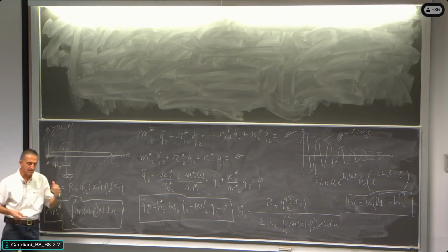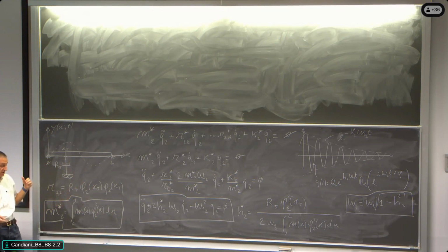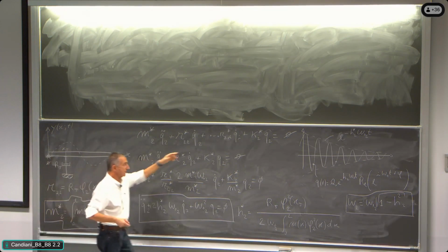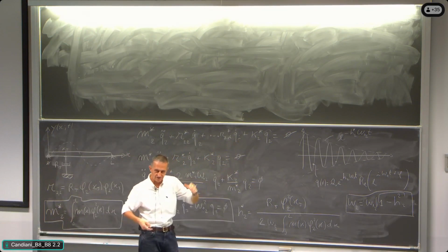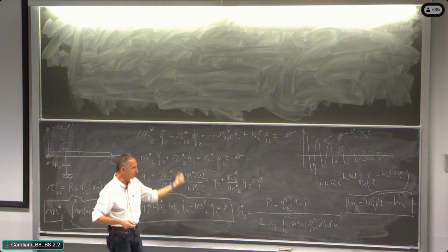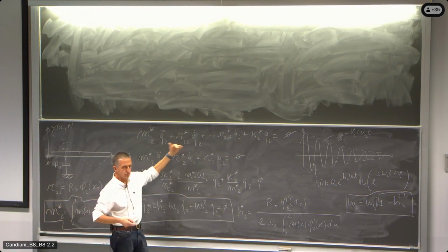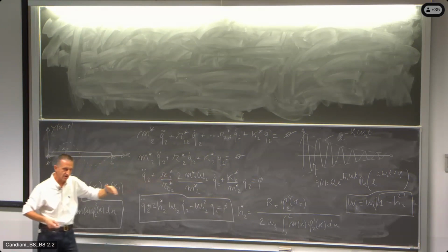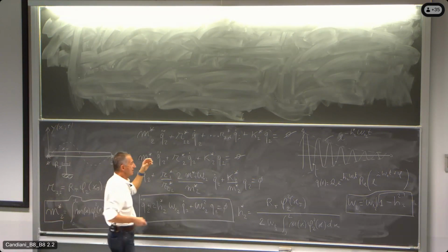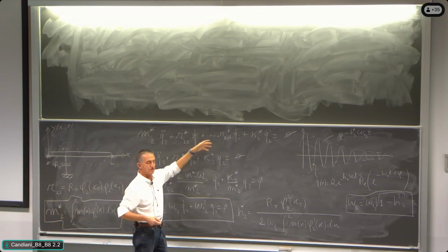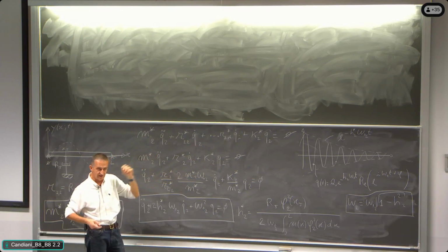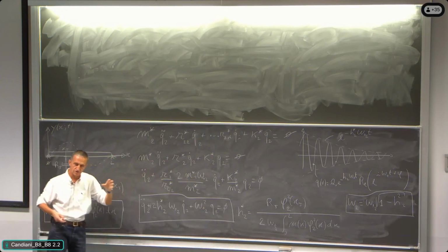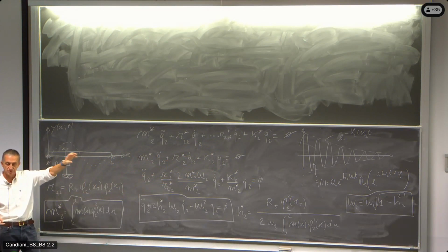So when the other modes are moving, so when the principal coordinates of other modes, for example the principal coordinate qi, are moving, for example because the mode i is moving, I have an input of work into the equation of the second mode, all right? And so there is some noise getting in. So it is not totally clean, the behavior of the mode 2. It's not just purely the mode 2 that will survive.